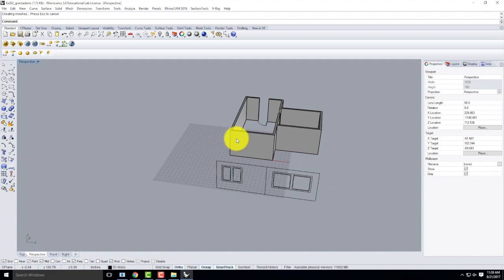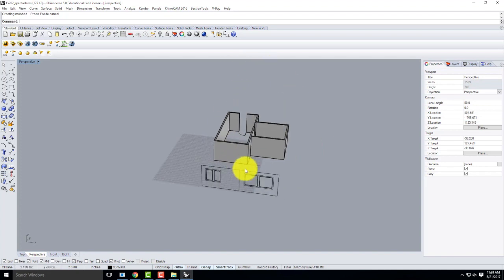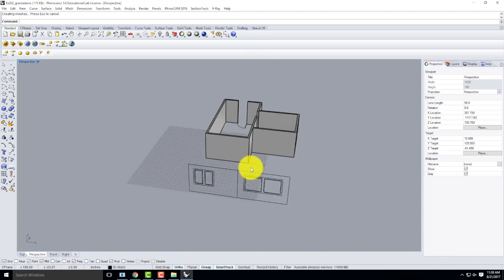And you guys had to deal with this a little bit in SketchUp if you took my version of 135, where we tried to move this close, or we tried to draw little guides or whatever to create this window. Rhino has something called the project command. At this stage of the game, you haven't used Rhino enough to understand how valuable this command really is. But what project actually does is it takes some curves that are floating out in space and it throws them at your building and draws it on your building, in this case.